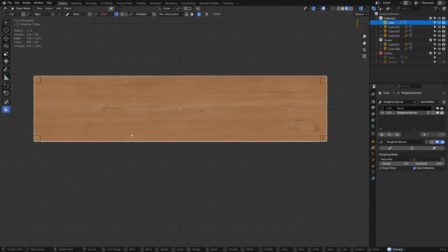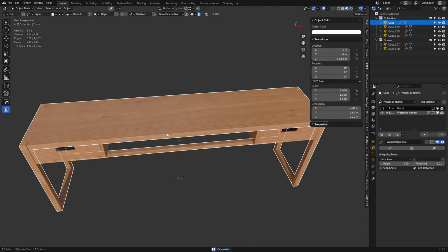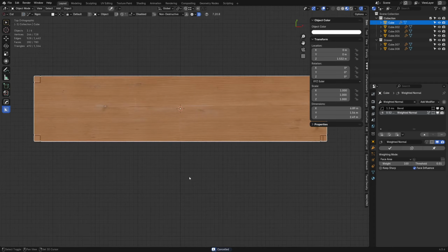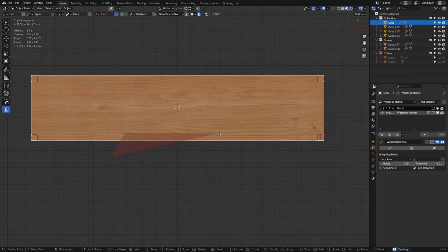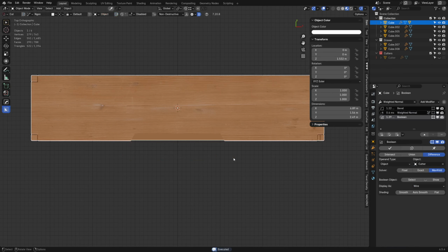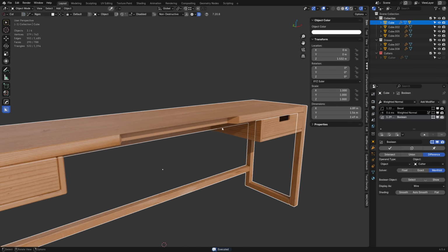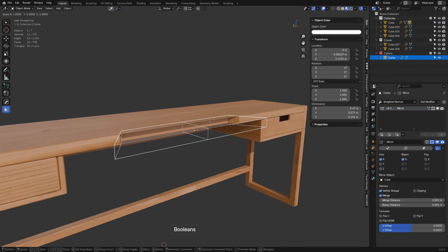Like if I want to cut. And boolean cuts you can do in vanilla Blender, obviously. We didn't use them, but if we want to do a boolean and mirror, which I guess we're getting some weird mirror action out of it. Should not be weird like that. Okay. Pressing 1 usually mirrors that way. I don't know why it mirrored all weird just a second ago, but it did. When I do that cut, I'm using a manifold boolean with Box Cutter. Hit Q, E, bring back the cutter, S and Z.